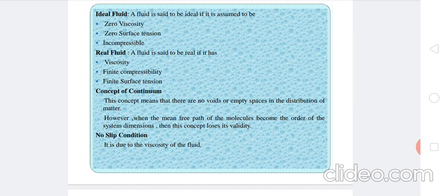Now, the concept of continuum. This concept means that there are no voids or empty spaces in the distribution of matter. Fluid is considered as a continuum as even in the case of gases, density is very high and the distance between successive collisions of the molecules is very small, meaning that the mean free path of the molecules is much less than the system dimensions. However, when the mean free path of the molecules becomes of the order of the system dimension, then this concept loses its validity.